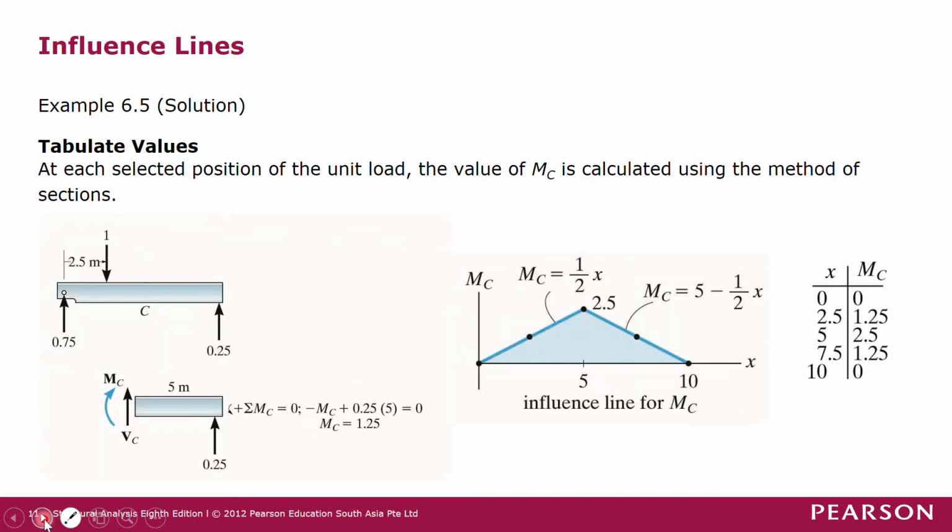If you want to tabulate values, at each selected position of the unit load, the value of MC is calculated using the method of sections.